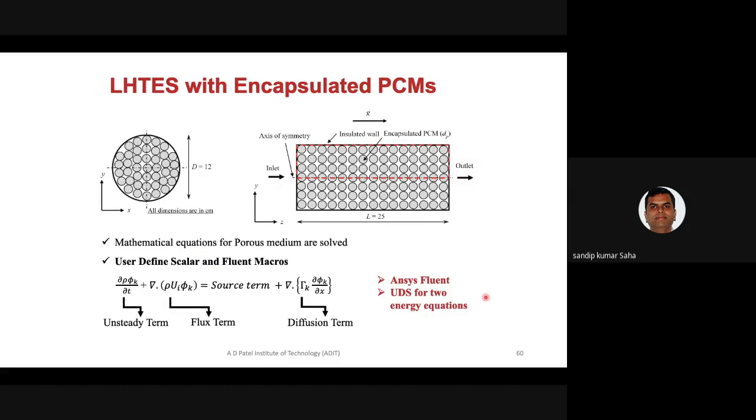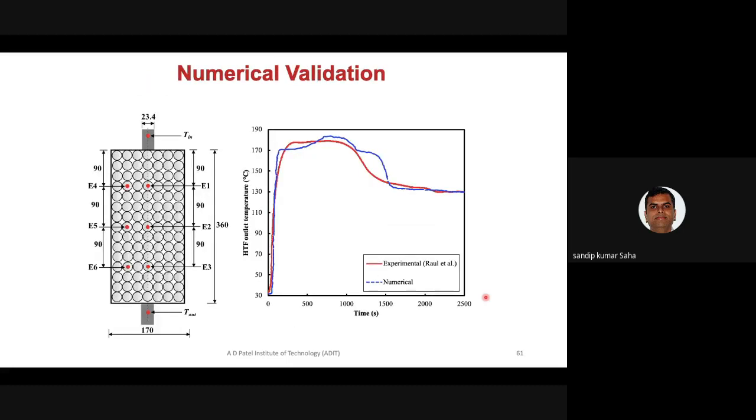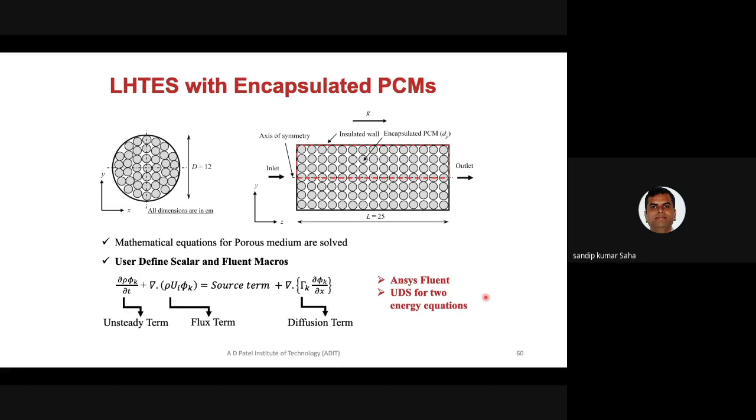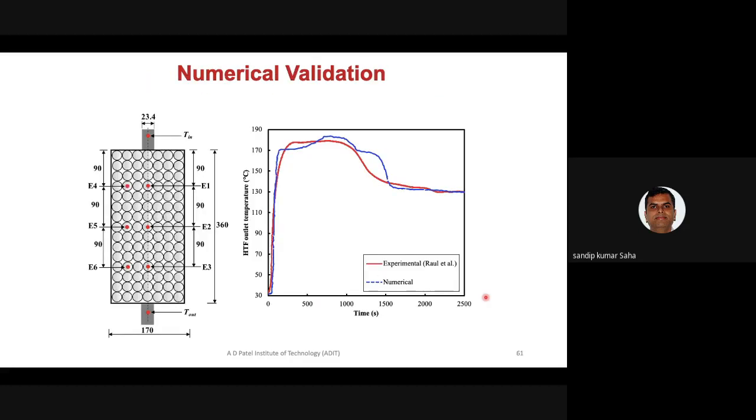Now, one simple model we have developed in our ANSYS Fluent. We actually developed this five years back, when Fluent did not have this model. Even today they don't have this module. So we have used UDF and UDS, whatever equations I showed you, to code the source term, and then we tried to validate with our own experimental results, and we see that fairly it is matching.